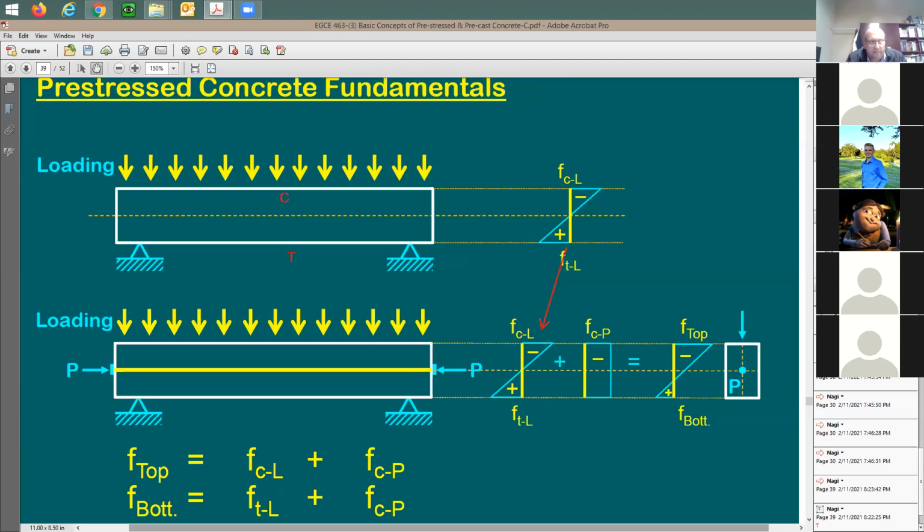It's bad. Okay, here's what happened. Just because of the loading, if you think about a regular conventional concrete beam, you're going to have this tension and compression before you add any compression to the concrete. And you know that concrete has a limit, after that it's going to collapse, right? So by putting the pre-stress in this location, right at mid-height, you actually increase the compression of the concrete and then reduce the tension on the bottom. So it is true that you did some pre-stress, but the big issue is you added more compression on the beam.